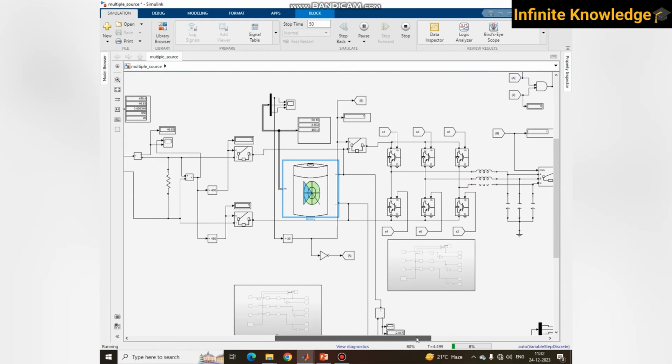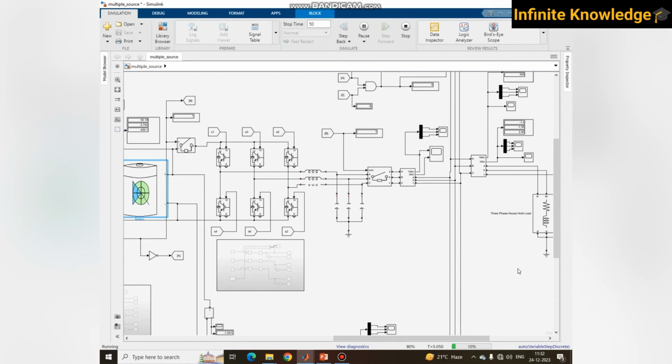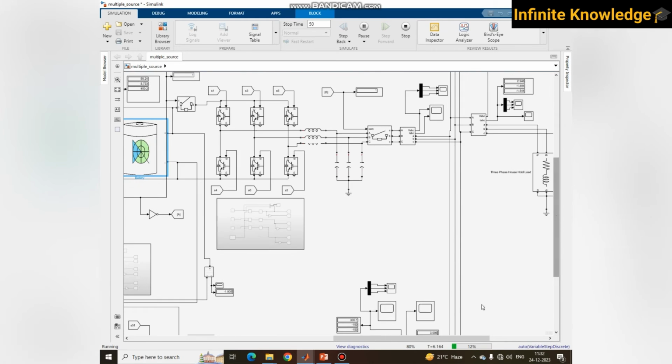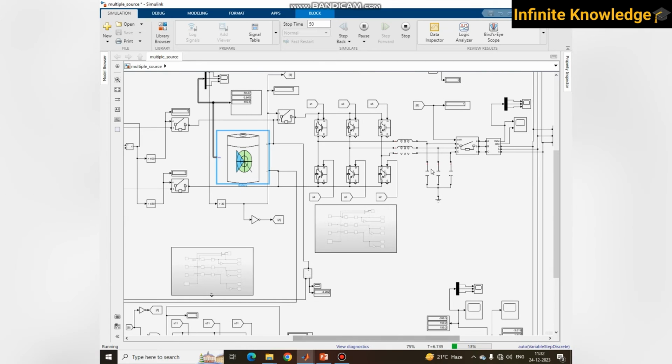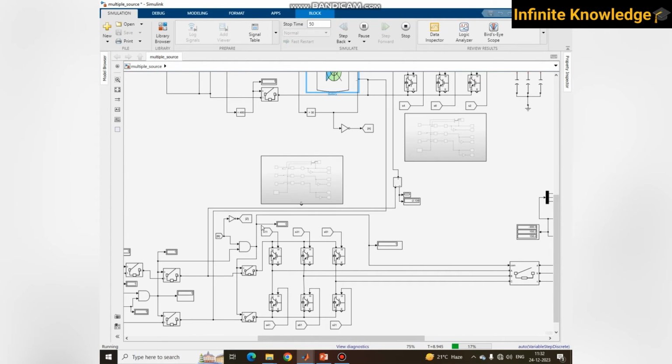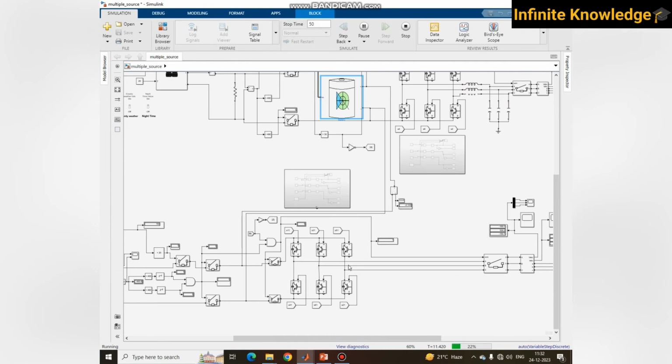In this condition, both solar and wind are synchronized and supply power to your load. Both breakers are on, and both voltages are proper. Here I have used a synchronizer, synchronized by this simple electronics circuitry. These electronic inverters in both supply sources cause better synchronization, because in synchronization the requirement is that your voltage level should be the same and your frequency should be the same. That is already the same because I have used the same inverter, and there is no back current or reverse current possible due to these diodes, due to these inverters.